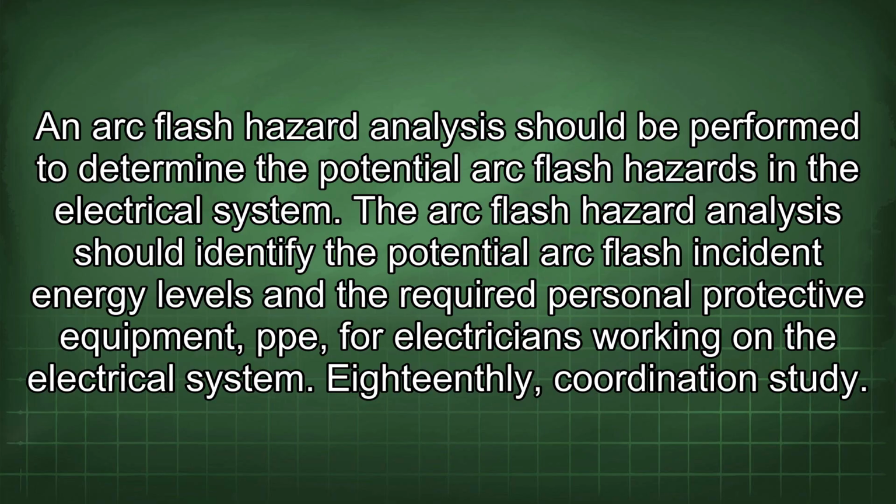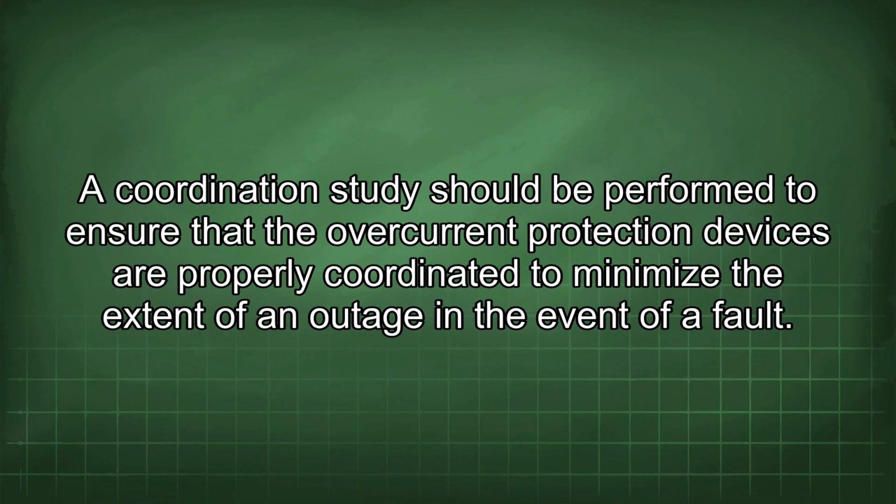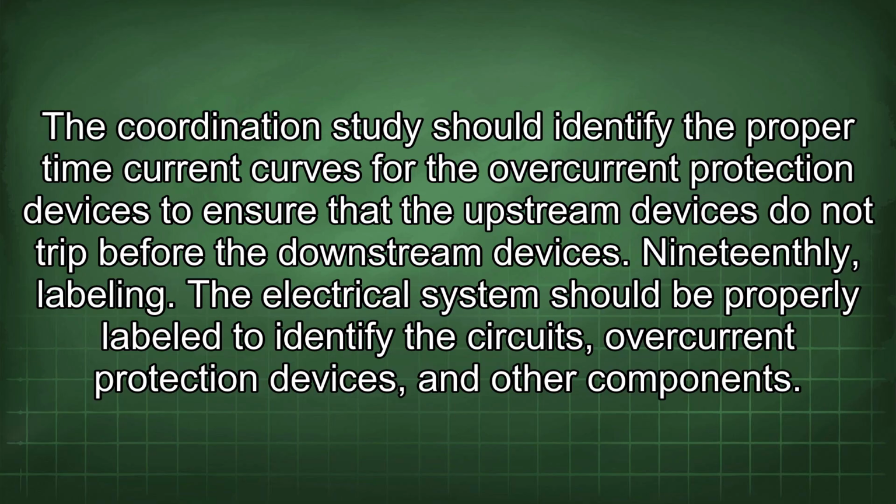18thly, coordination study. A coordination study should be performed to ensure that the overcurrent protection devices are properly coordinated to minimize the extent of an outage in the event of a fault. The coordination study should identify the proper time current curves for the overcurrent protection devices to ensure that the upstream devices do not trip before the downstream devices.